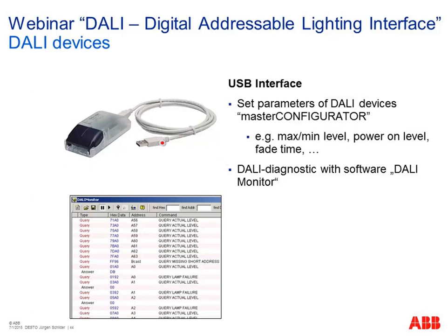This USB interface additionally allows, with another software called DALI Monitor, to see the traffic on the DALI. So we recommend using this DALI interface in installations where there are, for example, gateways to KNX. So we can send commands via our KNX sensor, and via this USB interface we can see the command in the DALI world. And then we see the gateway works correctly, or maybe there is a mistake in the programming of the DALI gateway, and so on. It makes sense, for example, to have this USB interface with you, and then we can see whether the command comes from the KNX world, yes or no, and also maybe the number of a device or the group, or switching the light on or off, and so on.